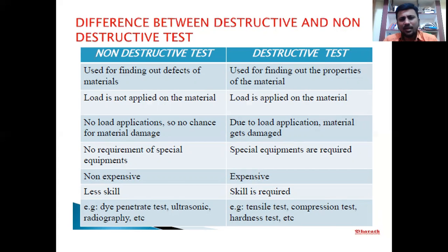Then, for the operating people, if you want to operate NDT methods, the skill level required is not much. Less skill is enough to check with the NDT method. But if you are operating destructive type tests, people need more skills. The skill level required is more for destructive type and less for non-destructive type. For example, in NDT there are dye penetrant tests, ultrasonic and radiography tests.